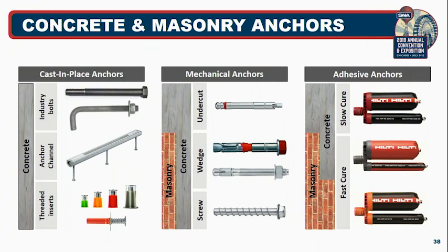With the screw anchor, since the installation process is to drill out the hole and use an impact driver to drive in the anchor to set it, if you need to remove the anchor, basically what you can do is flip that impact driver into reverse and back the anchor right out. So if you've got an installation that's not a permanent installation, you can set the anchors, and once you're done with it, reverse it and pull it back out. There are now some screw anchors out in the market that are reusable as well. They've got technology built in to be able to reuse that anchor, removable and reusable.